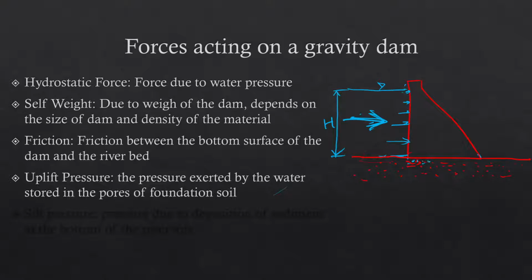So these pores will also be filled with water, and this water filled in the pores will also exert some pressure, and the direction of that pressure will be obviously normal to the bottom surface of the dam, and that normal direction is the upward direction. So this upward force is called the uplift pressure. We'll discuss this later in the lecture.